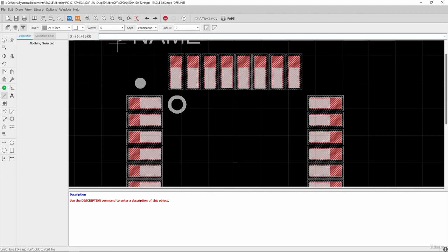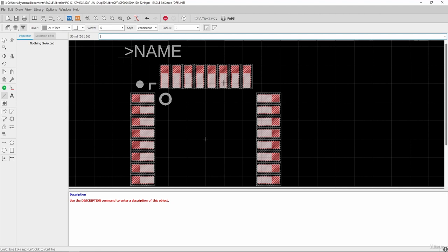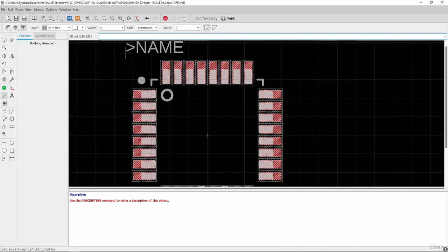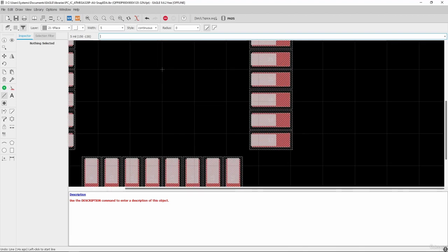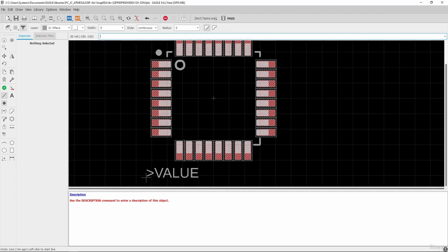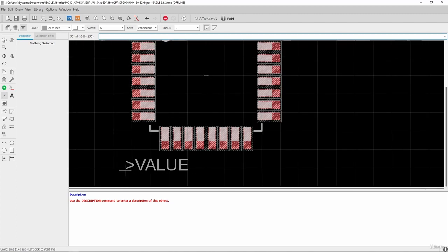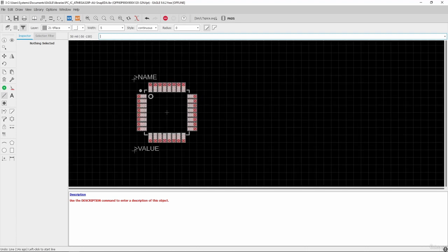Generally, whenever we create the footprint, there are actually some standards, and we need to follow those standards. It's not like you can create it in any manner. You need to actually follow the data sheet. In the data sheet of the IC, it will be given what the different specifications for the footprint are, like the size of the pad, the length of the pad, and the width of the pad. So considering all that information, you actually need to create the footprint. So that's how basically we do the changes in the footprint.